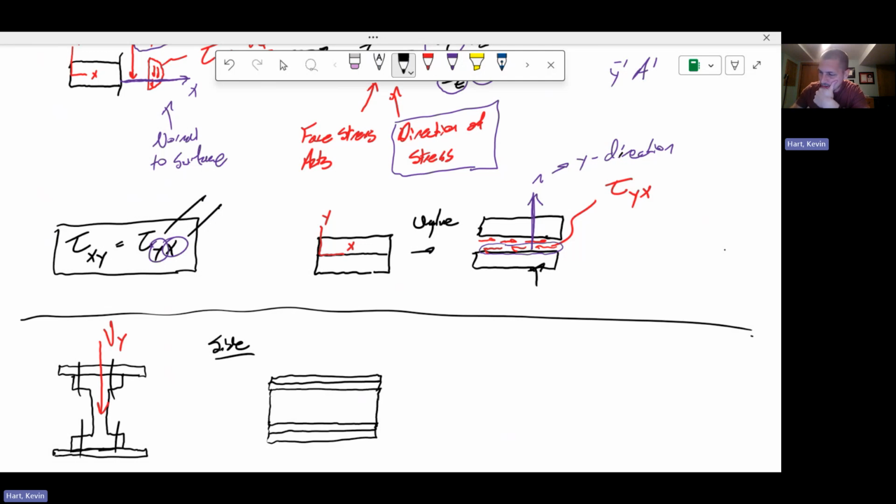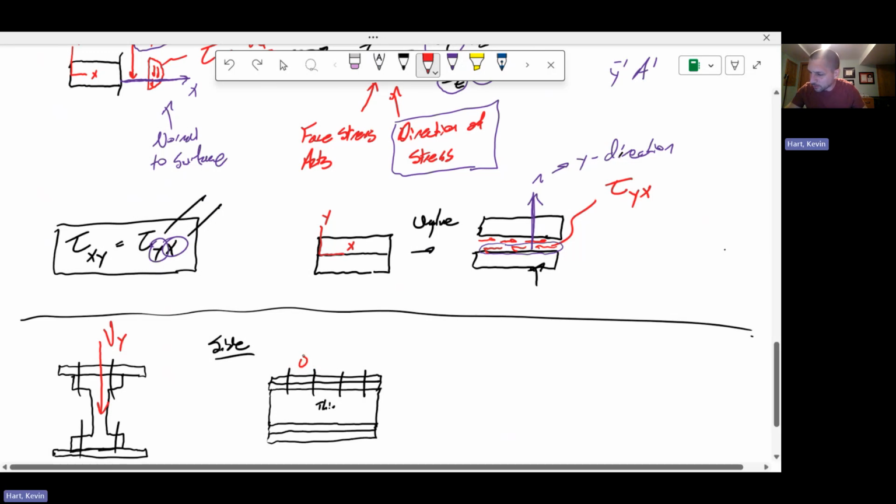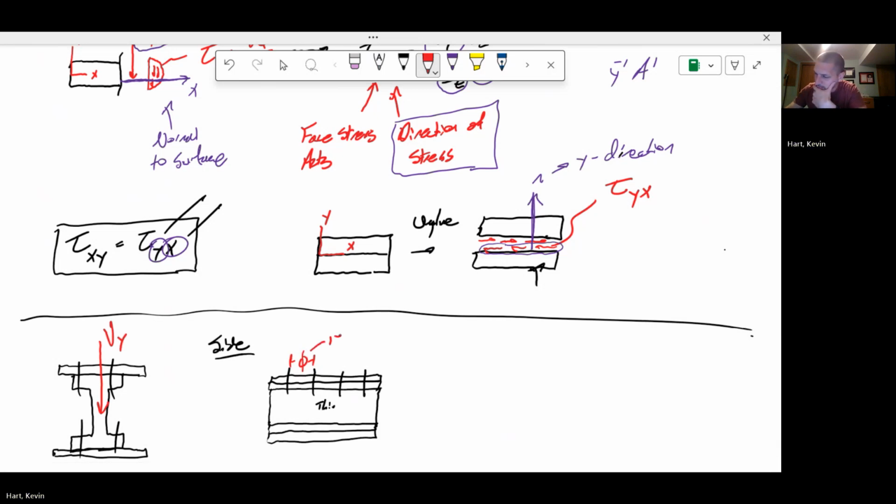So this is the thinnest part here right in the middle, right? So you've got these bolts that are holding this thing together, and they have a certain spacing. Let's call the spacing phi if you want. Call it whatever. This is phi, the spacing between the bolts, which is told to you is 125 millimeters. It's the longitudinal spacing of these bolts.